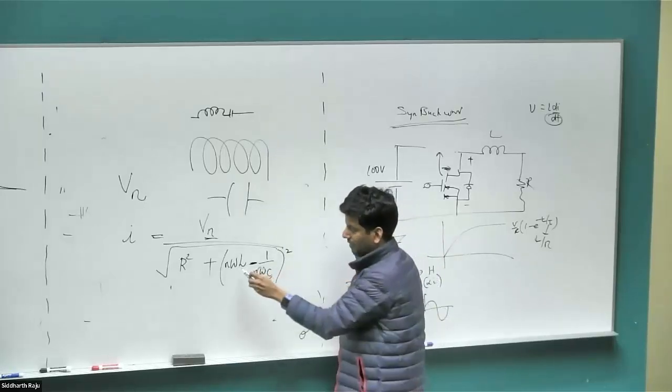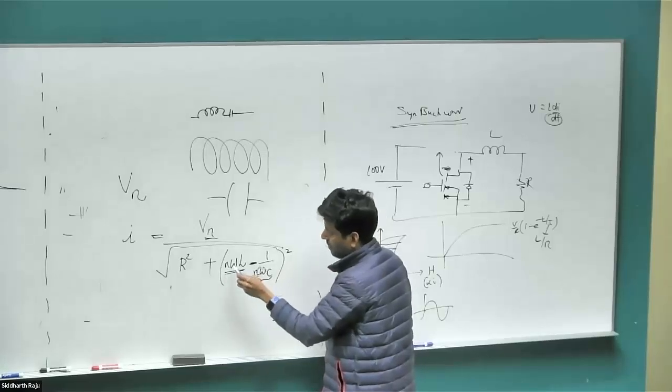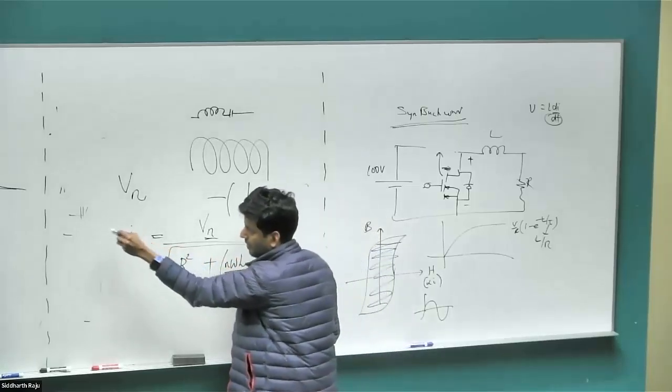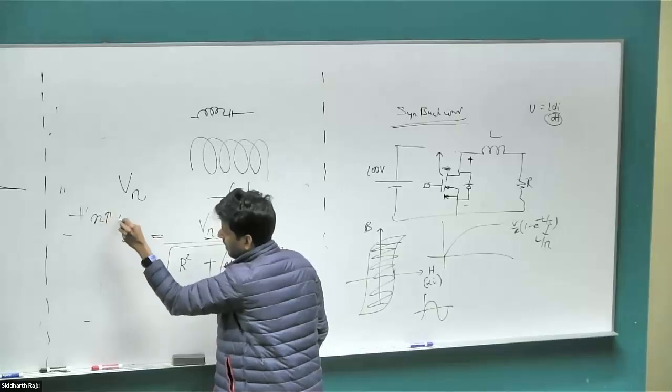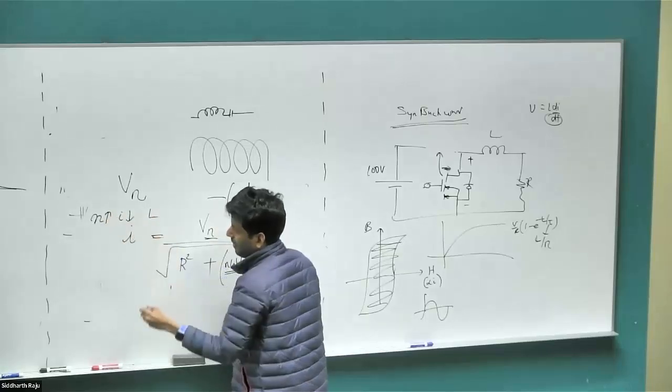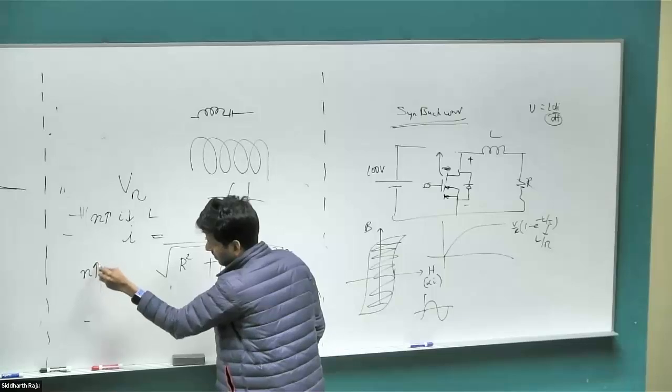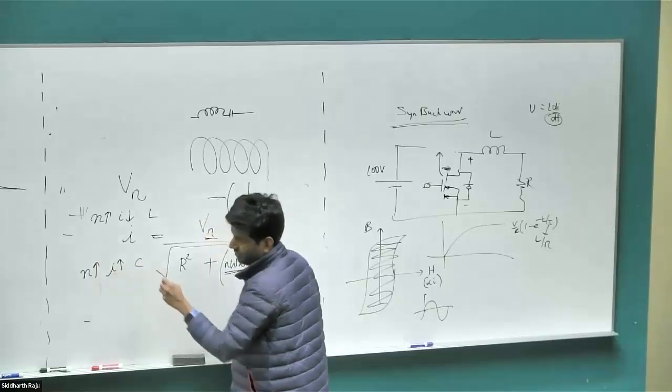Previously, when you had an inductor, as you went to higher and higher frequency components, the impedance increased, so the current went down. So if n went up, I went down for an inductor. But for a capacitor, as n increases, I goes up.